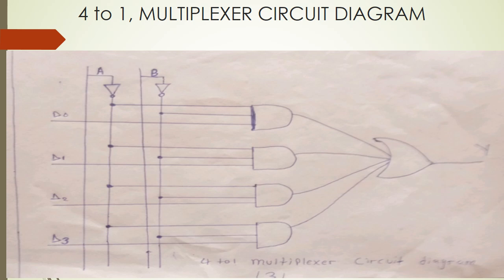The third one we draw out, which is our data input D0. We do the same for the second one: the first line goes to A, the second line goes to B, and the third one is drawn outside. That's how we did all of them, until we come to D0, D1, D2, D3. As we said earlier, a multiplexer accepts multiple inputs and gives out one output.